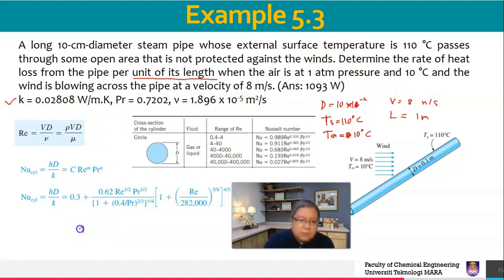First you have to determine the Reynolds number. Maybe we don't really care about the regime, because this kind of equation doesn't bother about what type of regime, as long as you know the range of the Reynolds number. But it is needed for getting this equation done, because it depends on the Reynolds number.